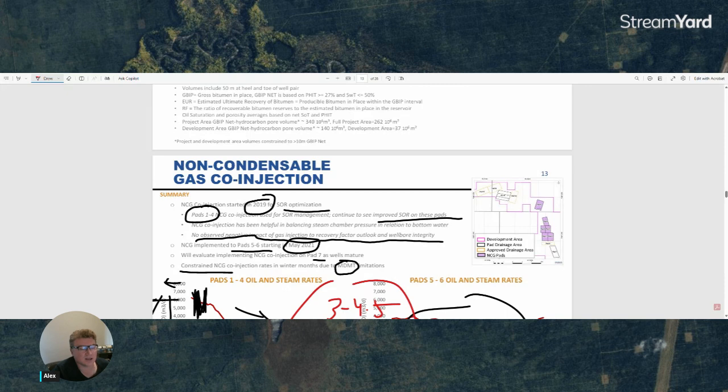Yeah, just to avoid cooling shocks, right? Thermal shocks, right? Yeah, thank you. Minimal design metal temperature, yeah. It's been a while since I've seen this term, and it's been a while since I talked about cooling shocks, but maybe that's what they want to avoid, right? So they don't want things to get too cool by reducing the enthalpy from the injected stream, to avoid cooling of the metals. So thank you for that.